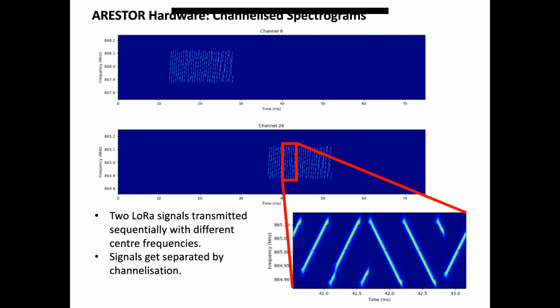And if we zoom in on a section of the spectrogram, then you can see why the thinning process is needed prior to the Hough transform, because these chirps in the spectrogram have a finite width. It means that you could fit a straight line through them at all sorts of crazy angles that you don't want. So ideally, you want to reduce each of these chirps in the spectrogram to be just a single pixel wide, so that there's really only one line that you can fit through them.